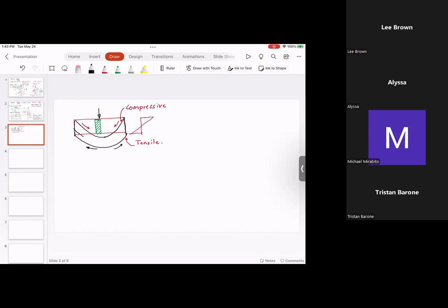And then there is something called the neutral axis. At the neutral axis, the fibers are neither stretched nor compressed. So we can state that the neutral axis does not have any stress. And the fibers that are on the top of the neutral axis and the fibers that are on the bottom of the neutral axis, depending upon whether they are stretched or compressed, you have tension or compression.